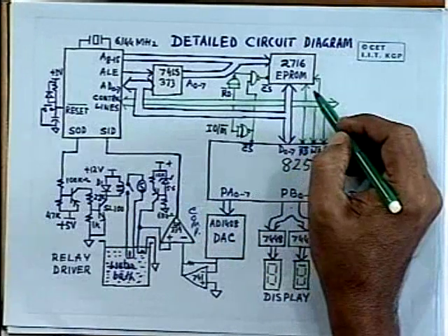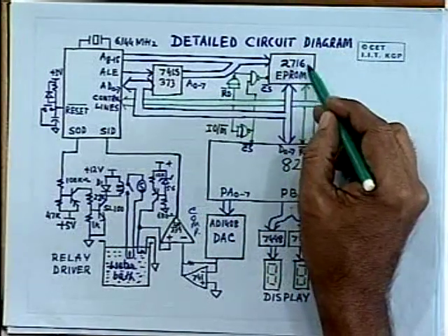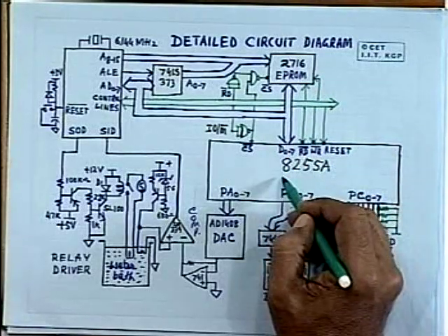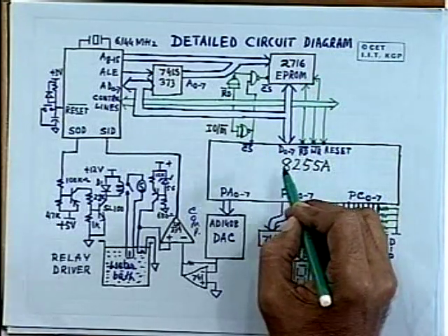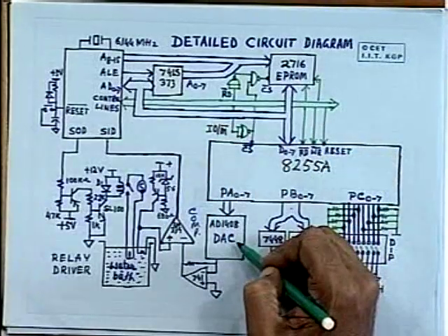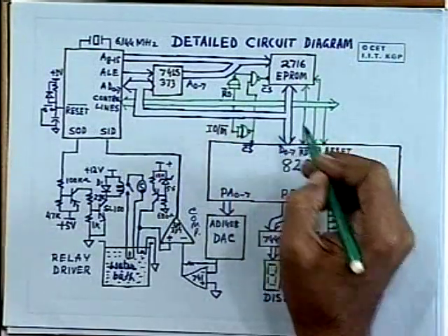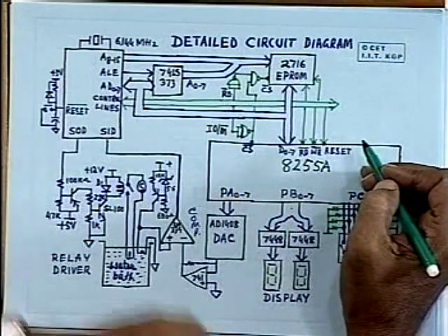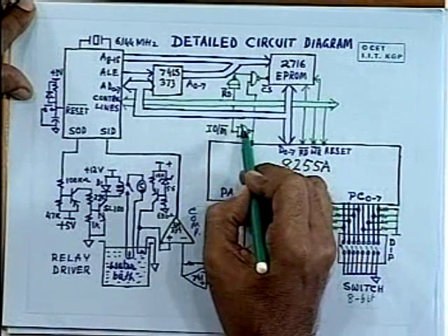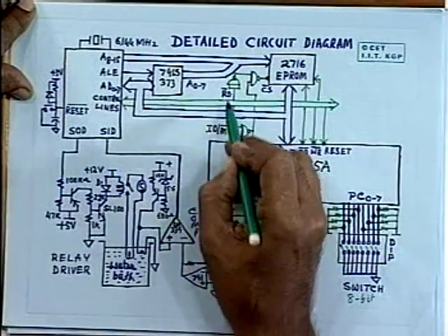And we have to now consider the selection of this PROM and the IO port chip. You have got only two devices connected to the system bus, as you can see, and the selection can be very easily done with the help of only the IOM line and the read line.